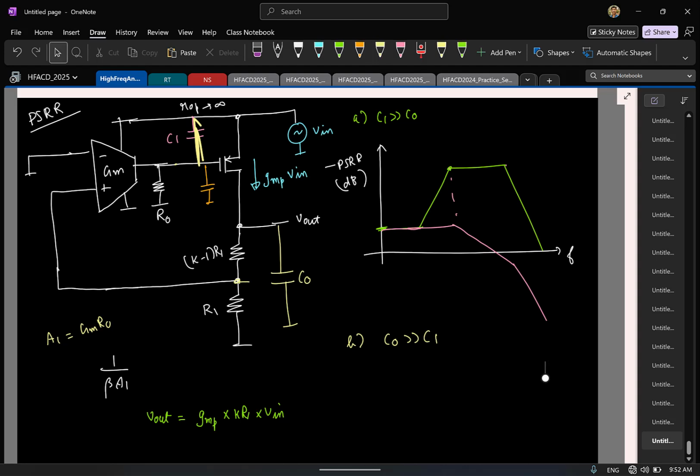So the point I want to make is this: an LDO or linear regulator is essentially a two-stage op-amp. So tomorrow if someone in your company asks you to design an LDO, you can't say that hey, this was not taught in my class. The same thing you learned for a two-stage op-amp exactly holds good, just that the metrics of interest are different, right? So here you are interested more in the output impedance, PSRR, etc. But whatever you learned with respect to poles and zeros, small signal will work.